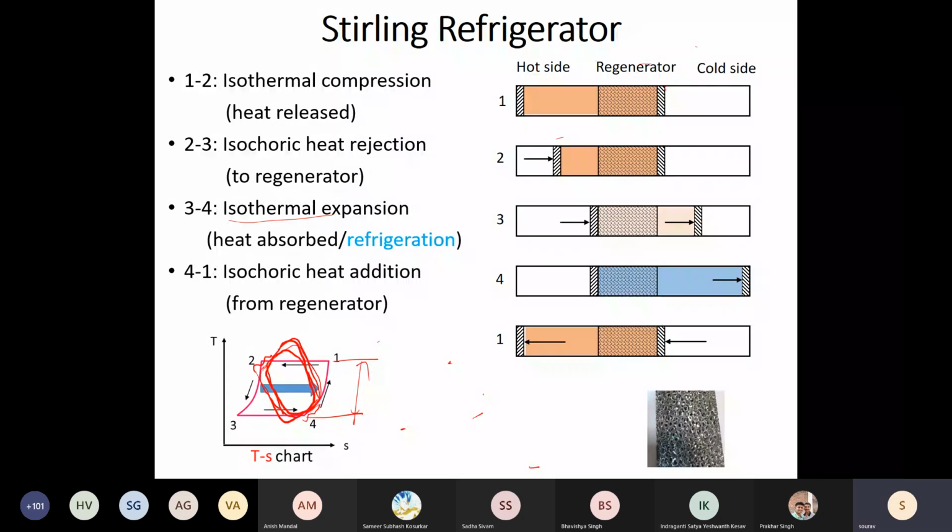First of all, the capacity will be limited by the mass which is trapped. So m into, this is what we discussed, na? M into. So this is still the ideal capacity. The amount of mass which is trapped inside this cylinder will be low because air or any gas has very poor density. So if you want to trap a lot of mass inside these two pistons, you will require a very large volume. That is one limitation. Next, RPS: you cannot go to infinitely high speeds also.